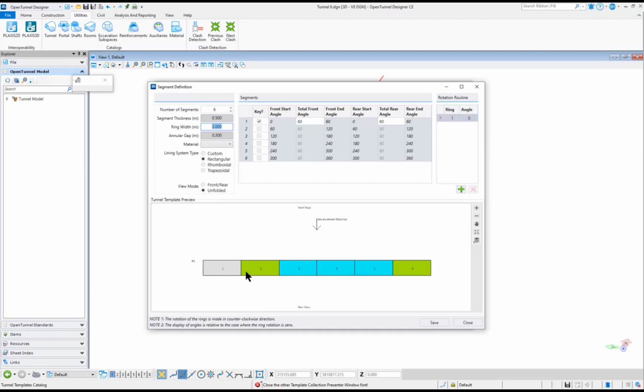So we can see the panels, and then rectangular is the rectangular form of each panel. Now it could be rhomboidal, and also it could be trapezoidal, and when it is trapezoidal you can give a different angle of the trapezoid as well, like whatever angle you like; I changed it to 10 degrees. And if I just put rectangular at this moment, for example, this is one strip and one circle.